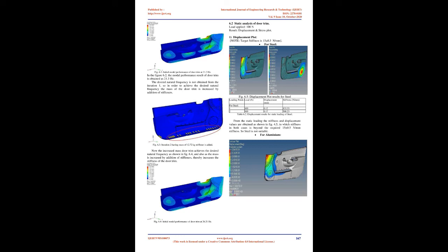Types of rigid elements: A. RBE2. B. RBE3. C. Bar. D. Beam. E. Rod. F. Spring. 5.4 Boundary condition for door trim. The door trim is constrained by SPC only in the translation direction, located exactly at the bolted regions which connect to the remaining door parts. The above figure shows a typical door trim constrained using SPC.